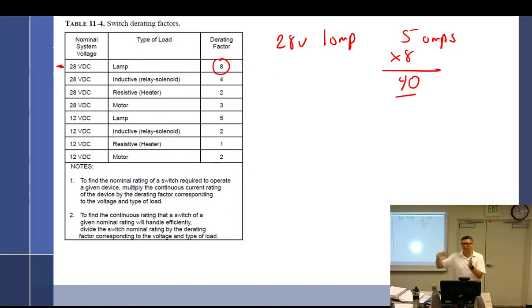Well, how in the world can we have a 40 amp circuit breaker on the same wire, when a minute ago we had it at 5 amp on the same wire? How does that work out? Is that jump in amperage only very, very short? There you go. Very quick. It's done. So if you had a 5 amp breaker in there, it's going to sense that and trip every time. So you have to placard it: in order to use this light, make sure you hold in the circuit breaker. But you don't have to hold it in for very long. Once it gets running, it'll be fine.